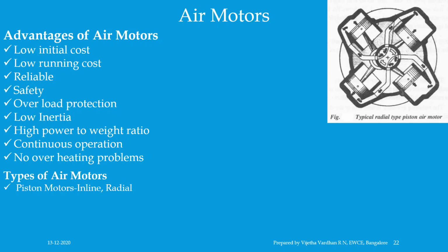Piston motors develop high starting torque, falling with the increased speed. Both torque and power developed depend on the supply of air pressure. Starting, optimum running and stall torques are also dependent on the supply pressure. Piston motors with variation in design include swash plate motors as well as face cam motors and other motors, but are superseded by vane motors.